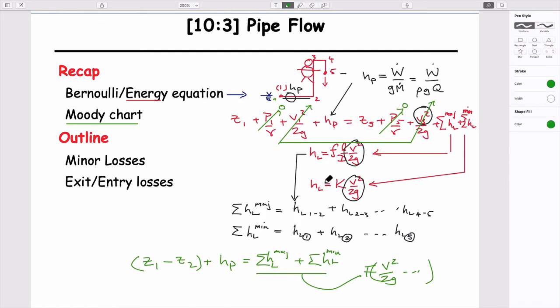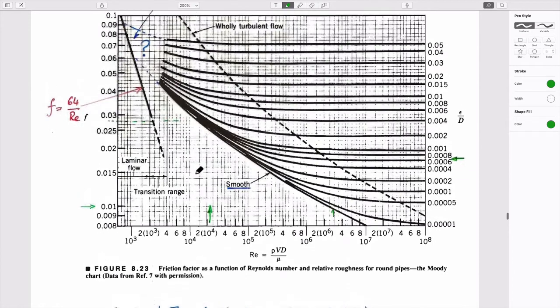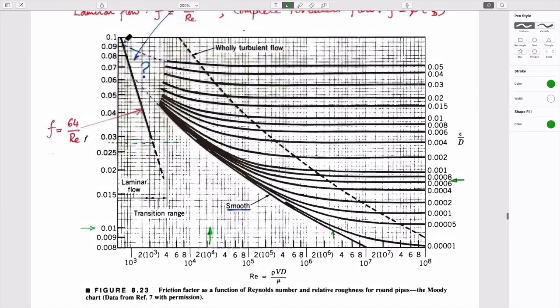It's relatively straightforward. Really, this figure absolutely encapsulates what those are. They never change from that. And it really says something about it which relates to the Moody chart. And I suppose that feature is that if we look at the Moody chart, the features that we know is that in the laminar regime, on this left-hand side, the friction factor, or the drag, so this would be the head loss, is equal to the product of friction factor, some characteristics of the piping system, and how quickly the fluid is moving in it.